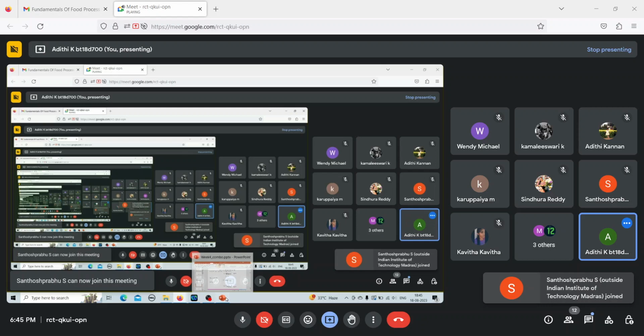HF is given as 2711.9 kJ per kg. It's just a basic substitution. With that, I am converting kg per hour into kg per second, so I am dividing it by 3600. So 2000 divided by 3600, into HF, which is 2711.9, minus HI. I am converting kilojoules into joules, so I am multiplying by 1000. Basically, I am bringing everything down into SI units. So with that, this is the power required, which is 48.11 kilowatts, which is option B.